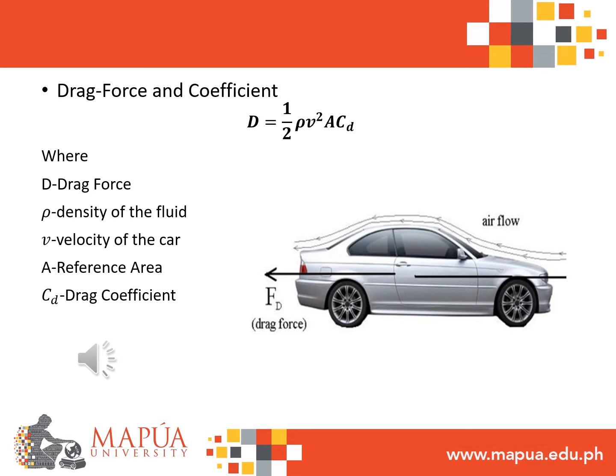In determining the drag force, there are so many factors needed to be considered such as shape, inclination, and flow conditions. For simplicity, these complex factors are characterized in one variable called the drag coefficient. The drag coefficient can be expressed as the ratio of the drag force to the force produced by multiplying the dynamic pressure and area. In comparison with the lift coefficient, determining the drag coefficient is more complicated because there are more sources of drag such as form, induced, wave, and ram drag.